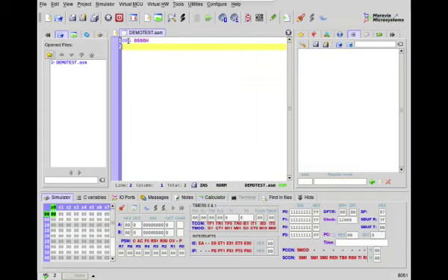Then we have to write sjmp start. Then the second thing is org 0040h. Then we have to write the label start, and from here the program will start.